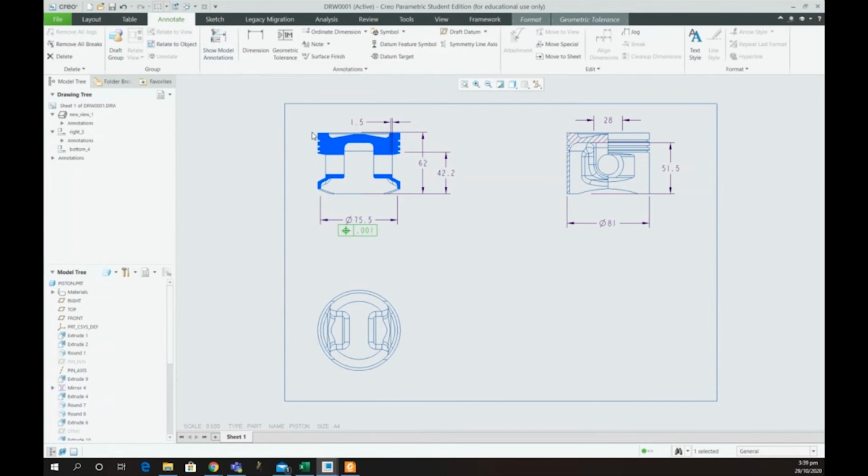The other thing which you may need is to provide if there is some particular surface finish over there. You would have to define it. If you want a more surface finish, like a really clean one for metals, that would mean the process would be more expensive. It would take more time. It would require more equipment and everything. So you don't do fine surface finish everywhere. You do it as it is required.